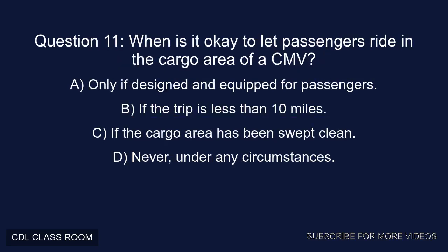Question 11. When is it okay to let passengers ride in the cargo area of a CMV? A. Only if designed and equipped for passengers. B. If the trip is less than 10 miles. C. If the cargo area has been swept clean. D. Never, under any circumstances. Correct answer, A. Only if designed and equipped for passengers.